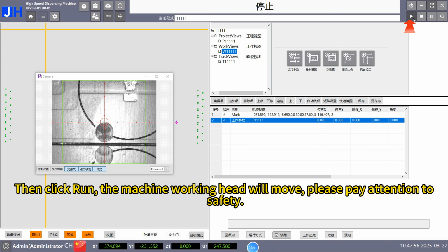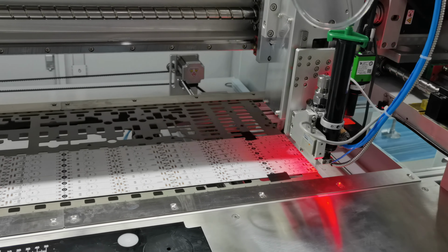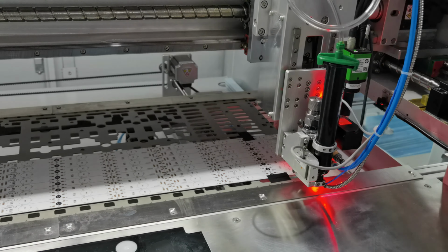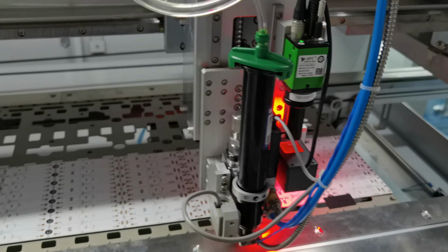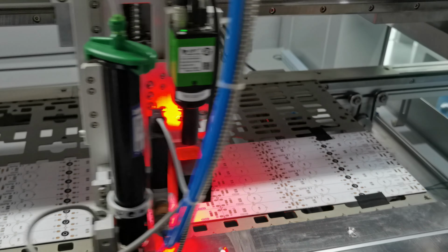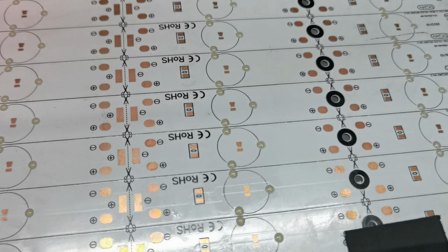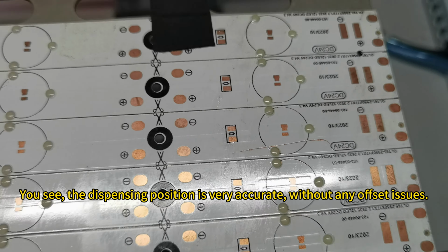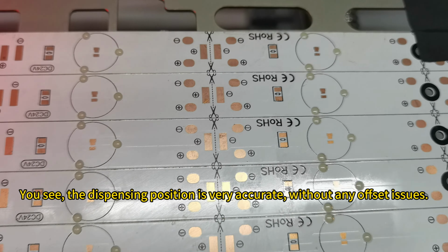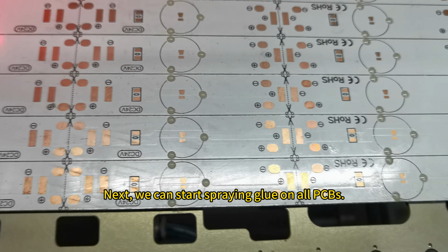Then click Run. The machine working head will move. Please pay attention to safety. We stopped the machine and checked the position of the glue spray points. You see, the dispensing position is very accurate, without any offset issues. Next, we can start spraying glue on all PCBs.